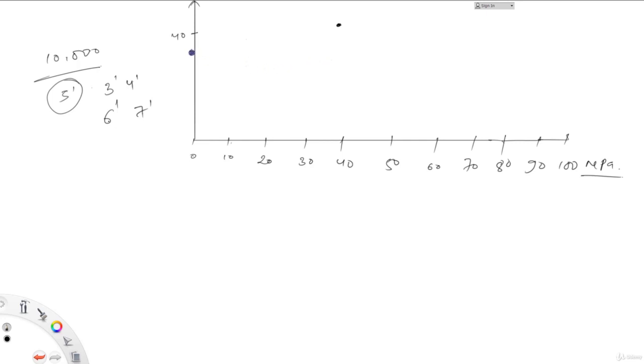So let's say that out of the 40, 15 cubes then show a strength of 30 megapascal, and 10 cubes show a strength of 20 megapascal, and similarly there will be cubes that will show strength lower than 20 megapascal. So why this happens is that when you make a mix, there might be some concrete cubes where the curing didn't happen properly, or where the mix wasn't made properly, or where there was a problem in transferring the concrete, and due to which it lost the strength. So due to this reason, this will fall gradually.